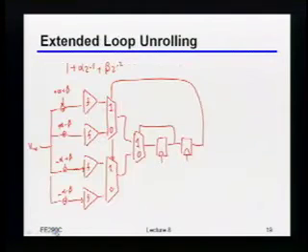I think only recently people started doing the second tap, but I'm not really convinced that's a worthwhile endeavor because, remember, all the power that you spend for everything in front of it is proportional to the amount of capacitance you've got here in the first place. And so 4xing the number of comparators pretty quickly adds up from a power standpoint. Okay, so indeed it can be done. I just wanted to mention this to make sure the concept was clear. But mostly you're probably going to at most do a one-tap loop unroll. Okay? Does this make sense to people?